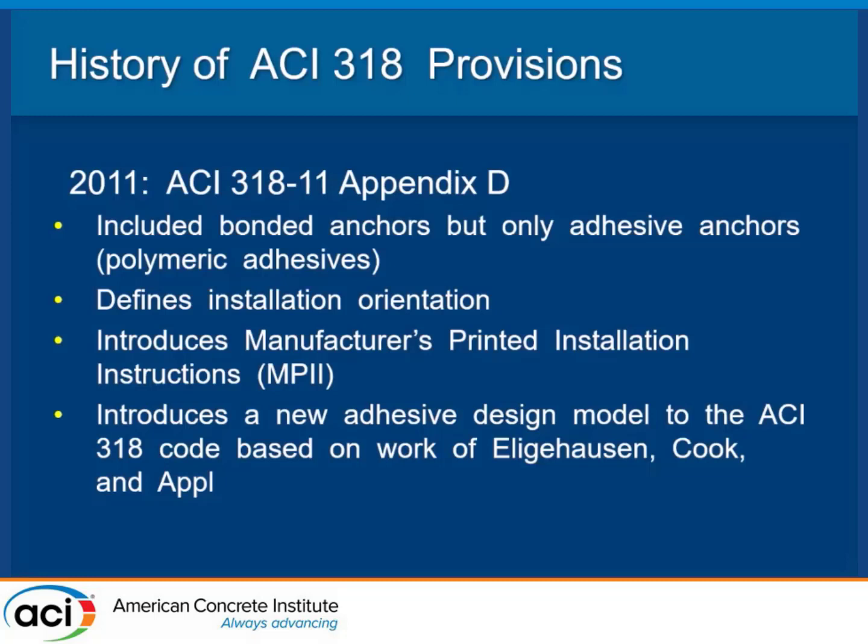And basically it says, if you're installing an adhesive anchor horizontally, inclined, or up above, we also require that the installer be certified. And we actually have requirements for inspectors to be certified. Why? Largely because of the Boston Big Dig, and doubly why? Because when you install an adhesive anchor, there are over 20 different mistakes you can make in the installation of that anchor, which will affect the strength of its installation. 20. I don't know if you can name me one just sitting there. So it's a much bigger problem than people think it is.